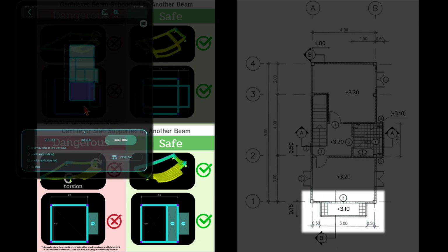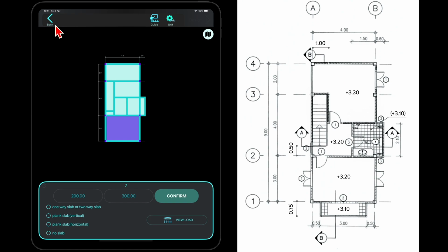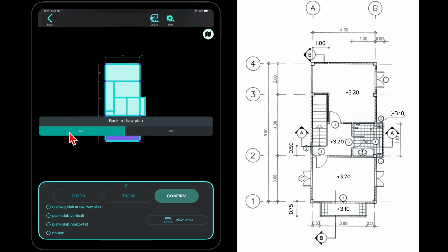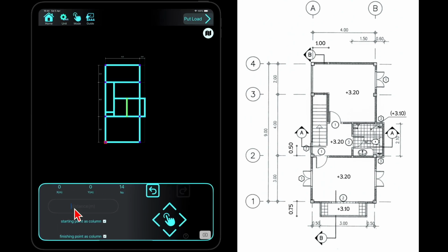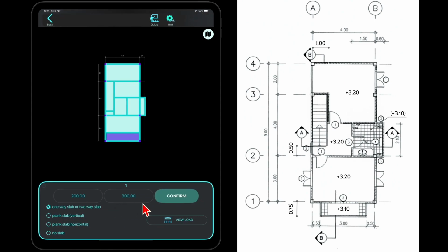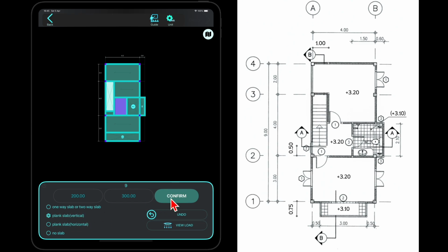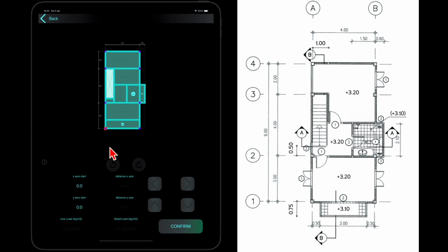Once the design approach is defined, go back and add beams to support the cast-in-place slab. Create the cantilever slab. Ensure all reference points and dimensions are specified.